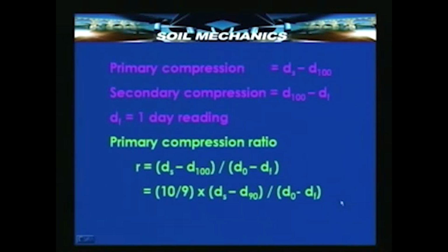The secondary consolidation phenomenon also can be mathematically expressed. It is usually a logarithmic phenomenon because it is a plastic deformation that takes place in the solid grains after the application of the load and at constant load, and generally therefore, it is expressed in terms of a logarithmic equation.